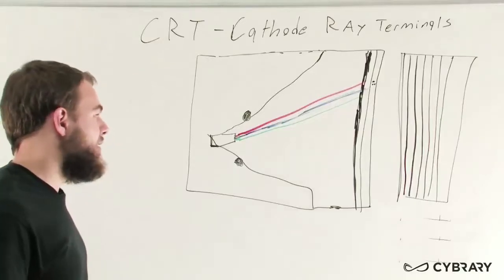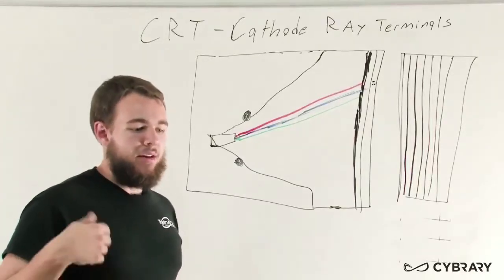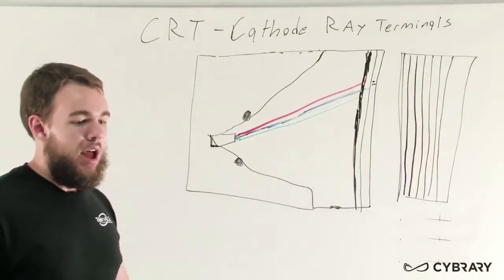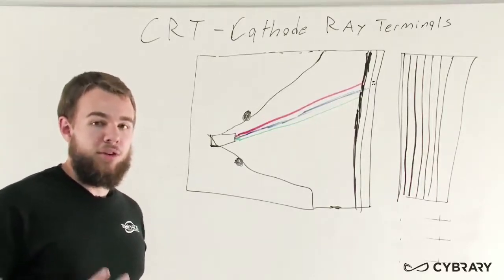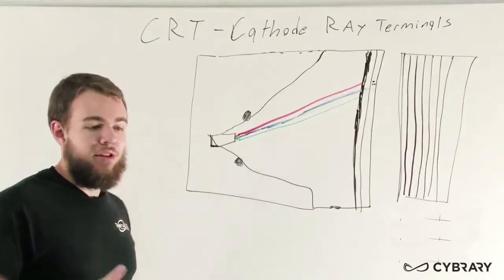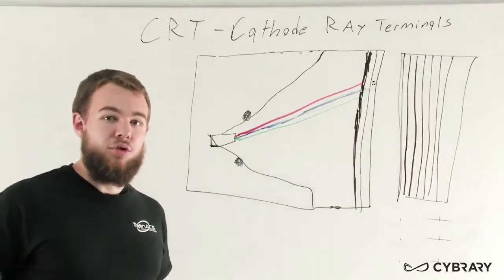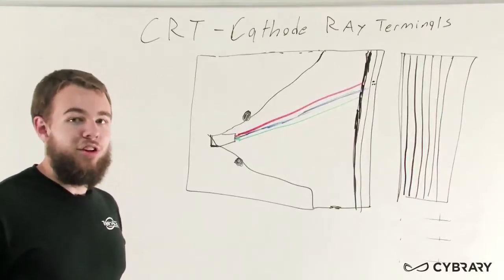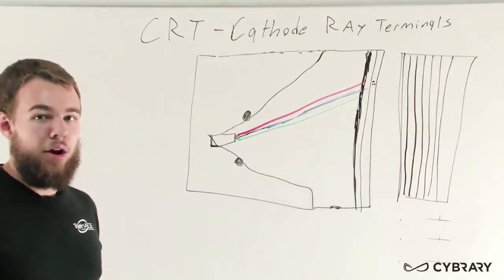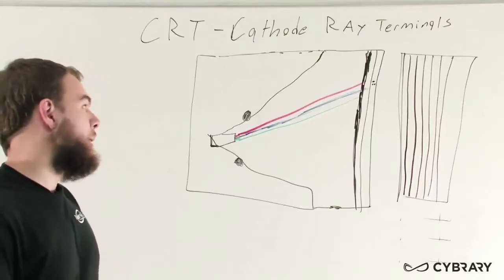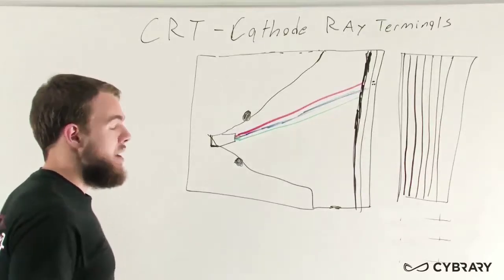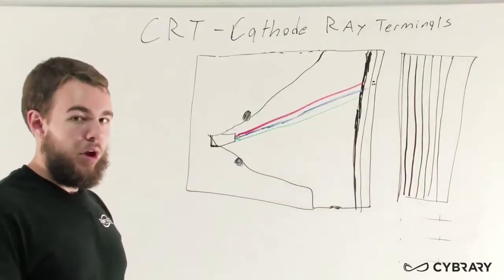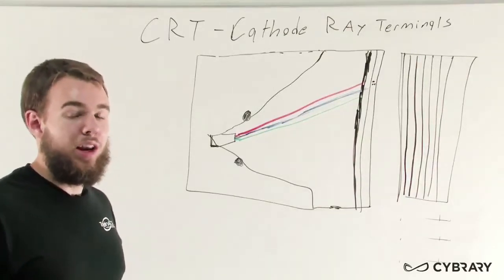Degaussing isn't something that we want to do all the time. Demagnetizing our display can actually reduce the life of our CRT monitor, and it can cause damage to the monitor over time. So while it is something good to do when we're noticing issues or possible slight distortion in our screen, we don't want to make it a habit to degauss our monitors just for the fun of it. We want to keep in mind that it is an option and something we can do, but we'll keep it to a minimum and do it when it's needed.